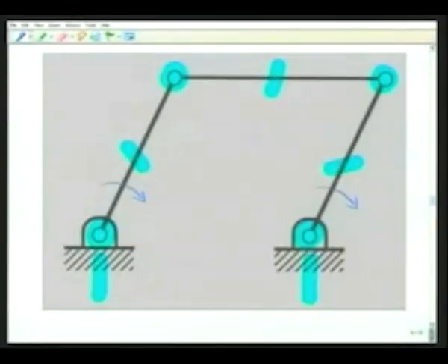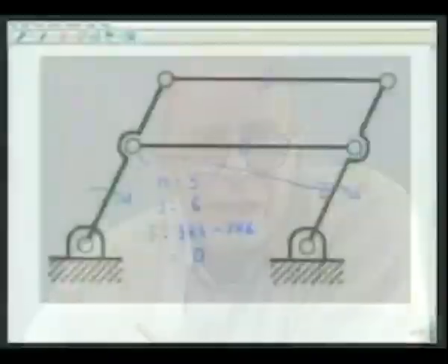In fact, such an extra coupler is normally used to drive a parallelogram mechanism. As we shall see in a model, when the parallelogram moves, there is a configuration when all the links become collinear, and that mechanism loses its transmission quality. In fact, it can go into a non-parallelogram or anti-parallelogram configuration. To ensure that a parallelogram always remains a parallelogram, such an extra coupler is necessary.